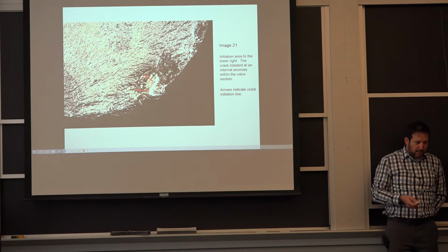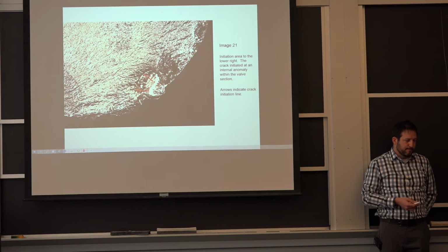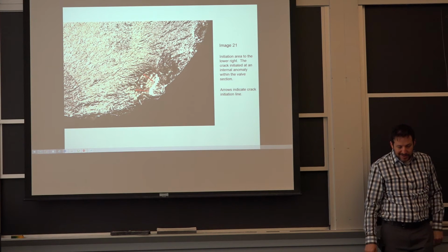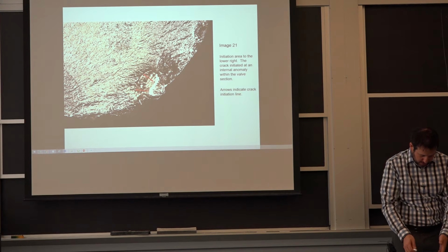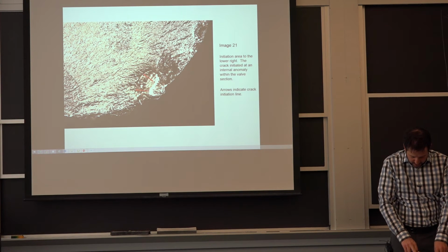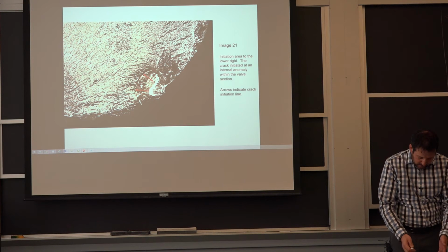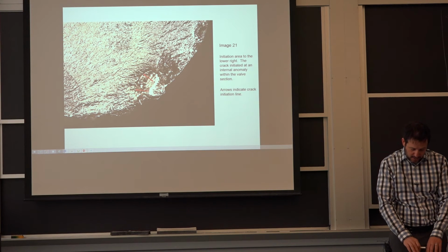The surface treatments for that are more in terms of steel. With steel you can create a lot of surface treatment, like carburizing, which will bring you a lot more yield strength on the surface. You take the part and heat it up in the oven, put it in a carbon atmosphere, and the carbon penetrates. You cool it off, and now you have a very hard surface on the outside, and you have a strong core.